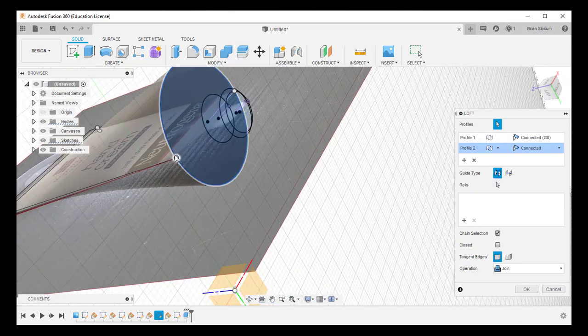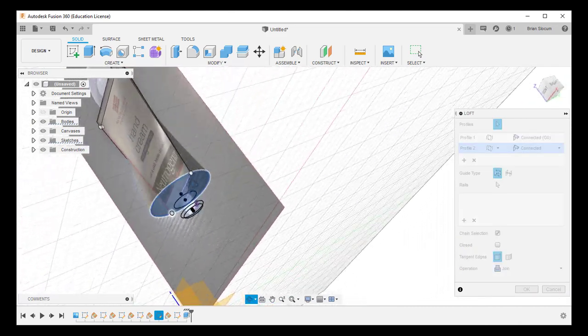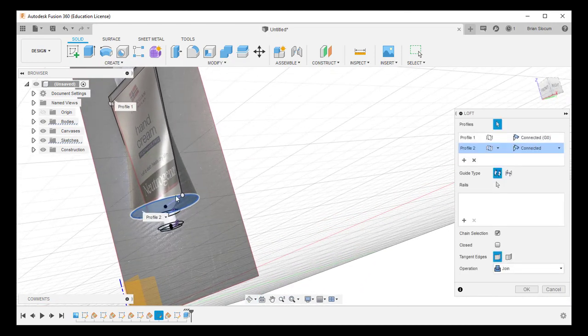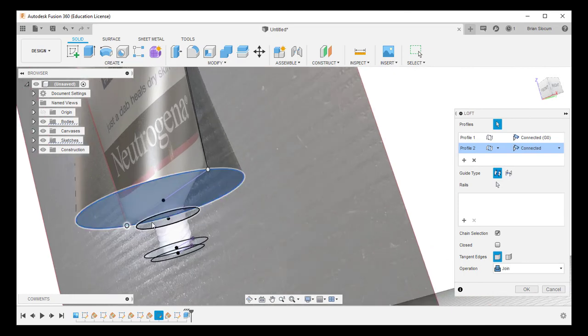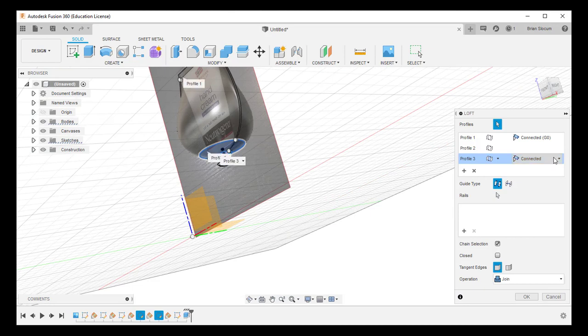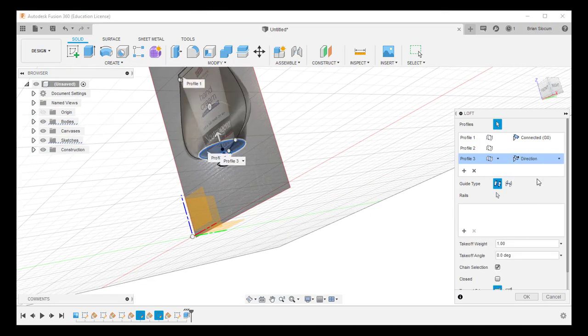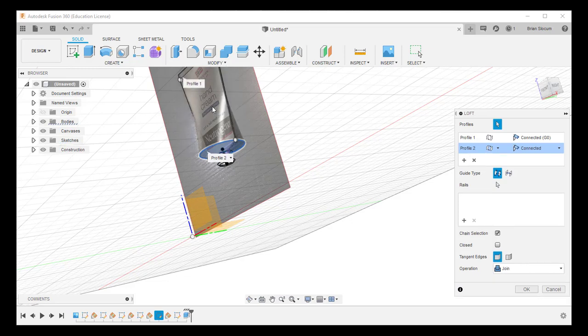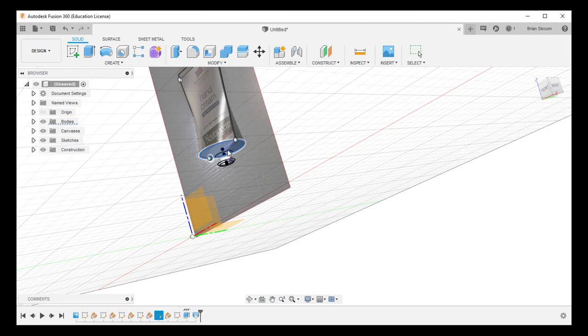Okay, so that cleans up that loft a little bit. And now I don't want to add another loft profile, because it's going to create a tangency around this point, and my tube's going to get really funny. So I'll show you if I choose another point. See how my tube has that funny shape? That doesn't work. Now it gets this really bloated profile. So I don't want to do that. I'm going to delete that third profile. That's the shape of the tube. And so the other ones are going to be independent lofts.